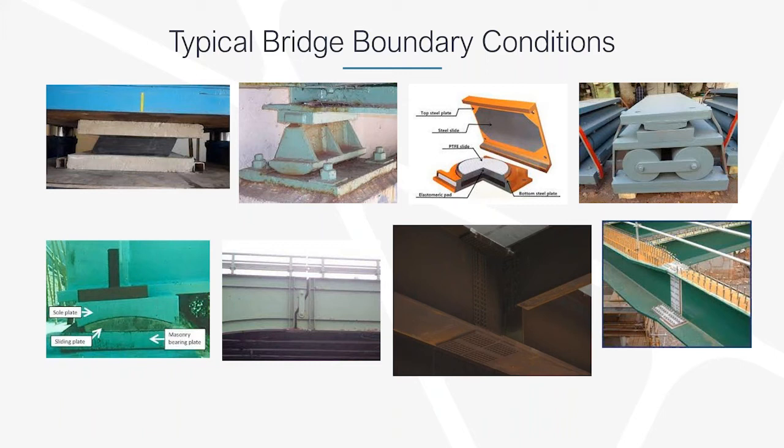And then these three on the bottom right are examples of an end condition for a beam. So there's the pin and hanger that is a way to release moment within the beam. And then you have a typical pinned connection between a framed-in element that you would treat also as a beam end release in a model. And then you have your splice, which is of course a fixed type connection. So just some examples of application.